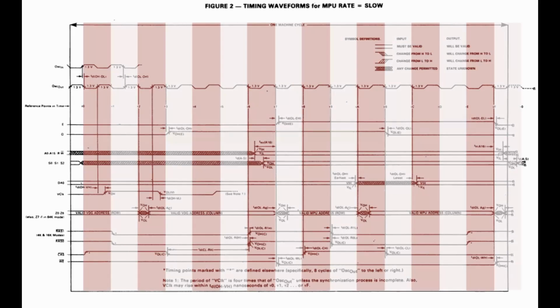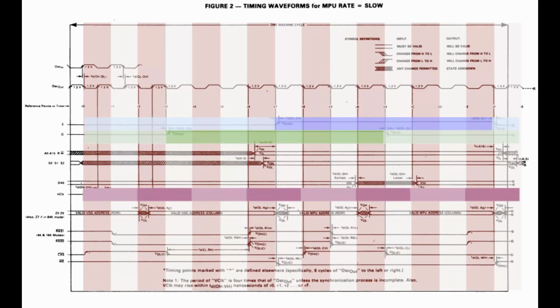To start with, the CPU clock is a quadrature system with two signals that are 90 degrees out of sync. The Q part is the warm-up act and prepares the CPU for action. The E part is where the magic happens and everything changes state. The CPU is only active for the high values of Q and E. The low values are used to provision the VDG, and when the VDG isn't busy, the horizontal sync, the low values are used to trigger DRAM refresh cycles. It also divides the master clock down into the video clock, with 4 video cycles for each 16 master clock ticks.